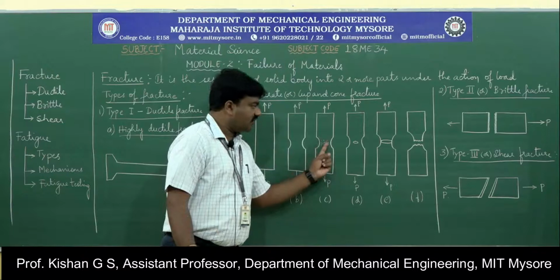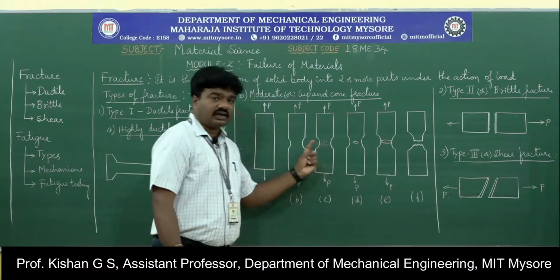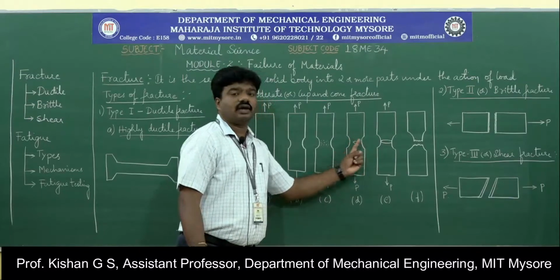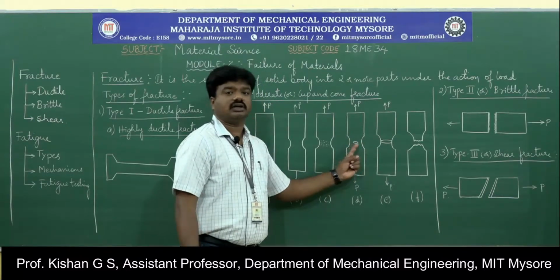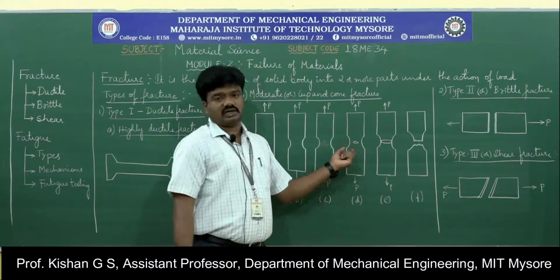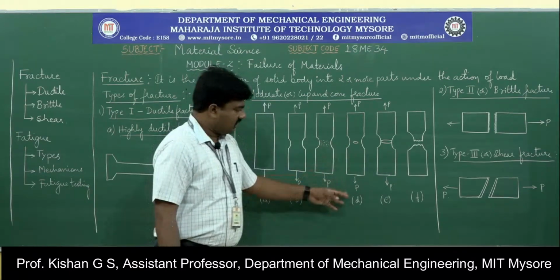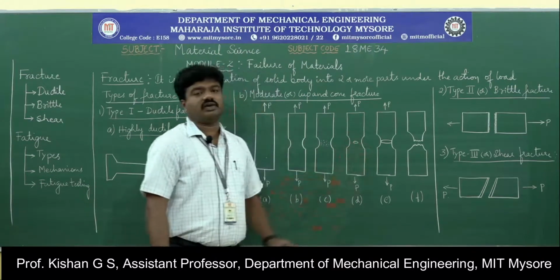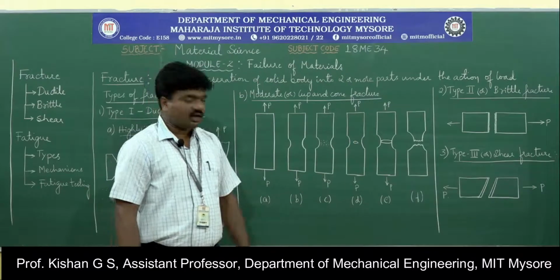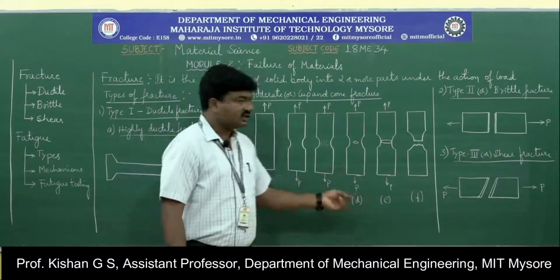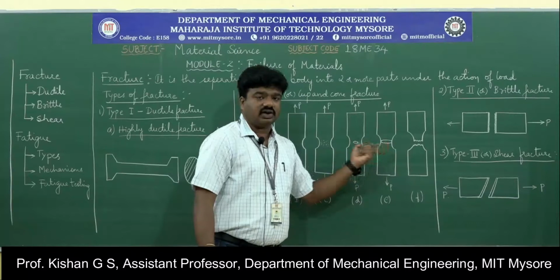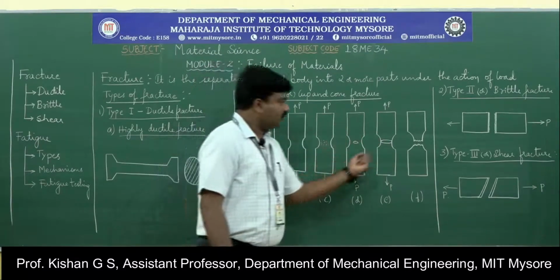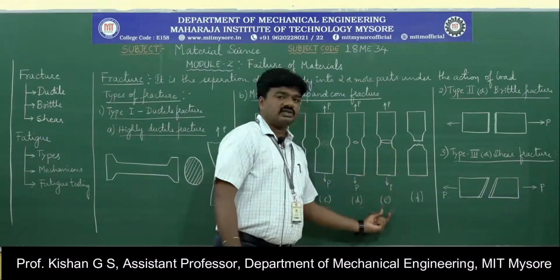These small cavities or voids collectively result in the formation of an elliptical hole or elliptical cavity or elliptical ring within the neck region itself. So here in position D or stage D, we can observe the formation of an elliptical cavity or elliptical ring in the necking area. Upon further increase in the load, this cavity gets extended along its axis and results in the point-to-point cavity in the complete necking region which is observed in this stage E here.